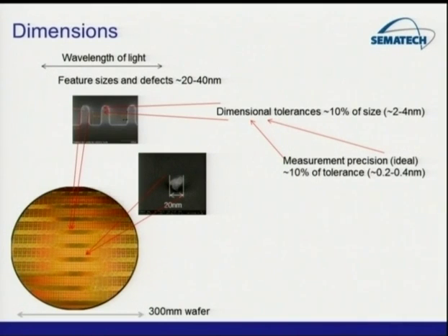Next generation wafers are a little bit bigger. They're 450 millimeters, so 18-inch pizzas instead of 12-inch pizzas. But more importantly, going back to that roadmap chart of about 22 nanometer manufacturing today, the size of the features we're trying to measure on each of these transistors is somewhere around 22 nanometers. There's a little bit of range there because the different layers have different thicknesses.